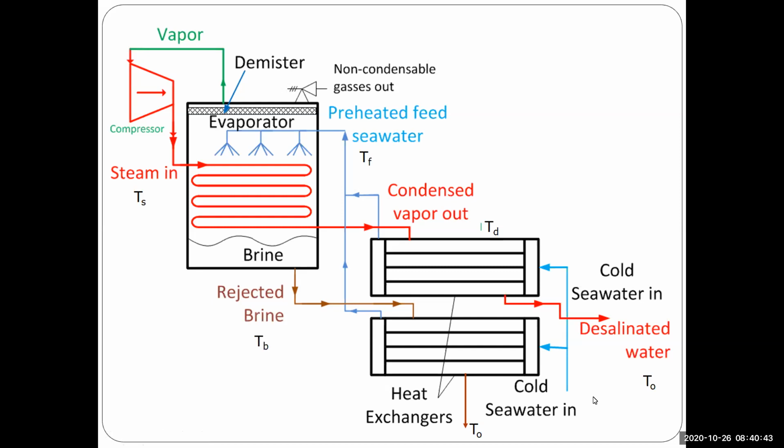On the other hand, we have T cooling water, which is coming in here, that is going to be heated up to T F, which is the feed temperature. We do not need an additional quantity of seawater. Remember, in the condenser, we said that we need the entry to be T cooling water plus T feed. The T cooling water will enter in, it will be preheated, and then we throw it away. And the reason was to make sure that all the vapor is condensed.